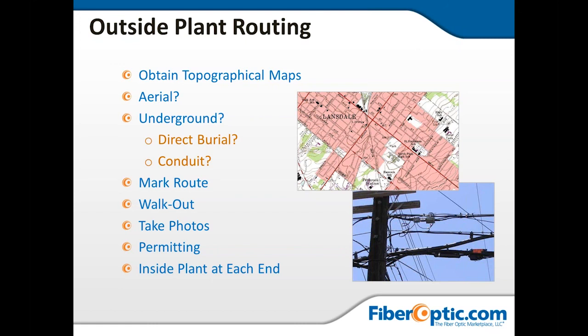Are you going to go aerial or underground? Again, direct bury, which is never my first choice, or are you going to bury conduit? Direct bury does have some benefits in cost, and you can usually use a plow to lay it, rather than having to dig a trench. So in fairness, while I don't like it, there are times when it is the most economical. So I will concede that point.